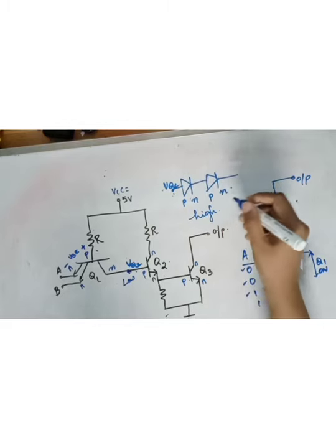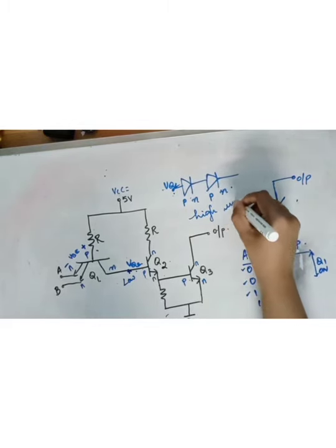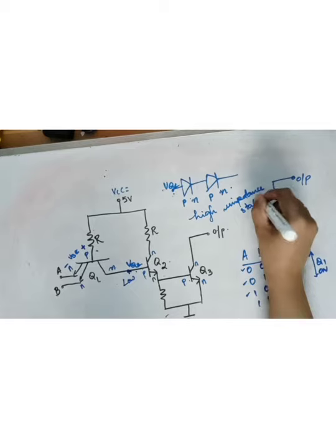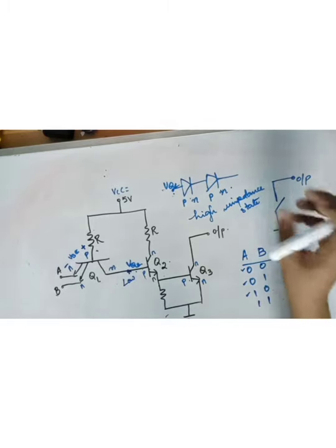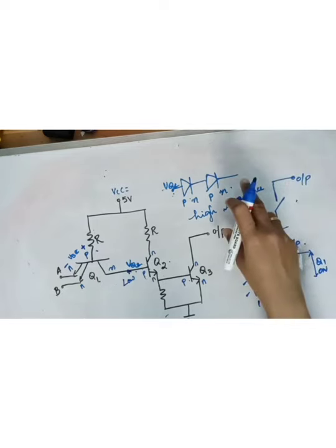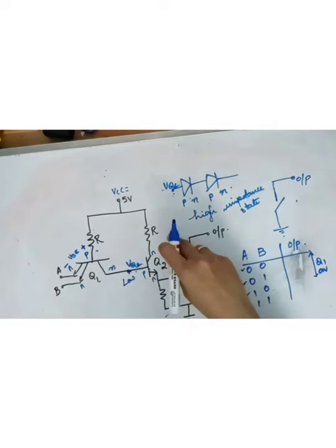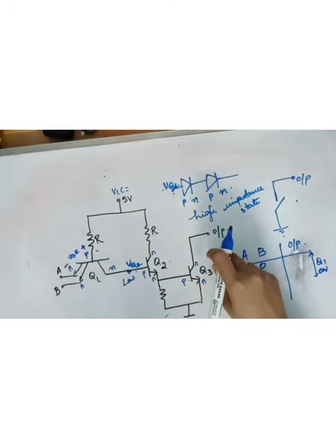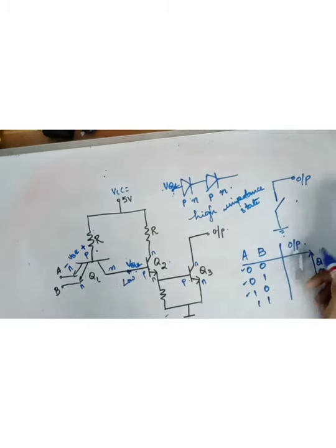High impedance means what? Resistance. High impedance state. That is an open circuit. High impedance state is just an open circuit. So in an open collector TTL, if one of the inputs is 0, then the output is in high impedance state. That is denoted by Z.